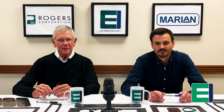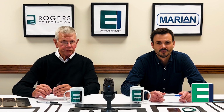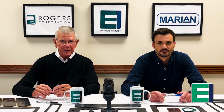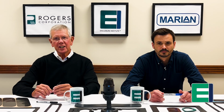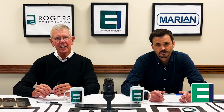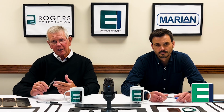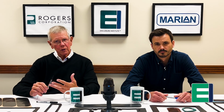As we've said before, many gasket materials will seal well on day one, but understanding how a material will hold up over time in challenging conditions could help you to make the best choice for the expected life of your product. Today we'll discuss three common environmental conditions that can have a negative effect on the polymers of foam materials: oxidation, hydrolysis, and UV or ozone.